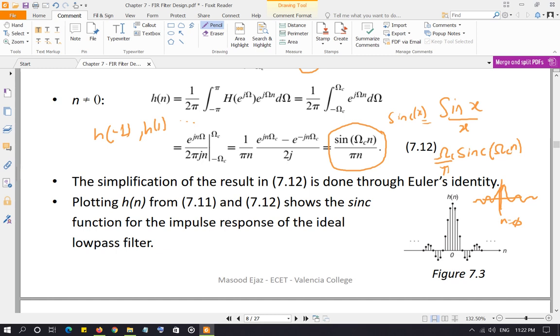So even theoretically, in communication systems, you discussed that when you're creating even an analog filter and considering an ideal analog filter, the time domain response starts before n is equal to 0. It's a sinc function, and that's why we say that even theoretically it is impossible to conceive an ideal filter response. And of course in practice, you know that we don't have an ideal filter response, although we can go close to it if you start increasing the order of the filter, as you will see soon.